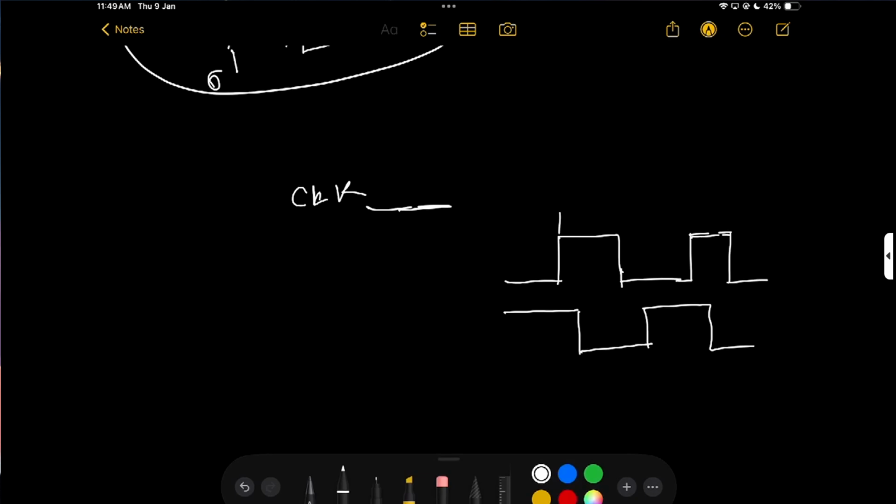So in here, in a short duration, I trigger the circuit such that my circuit is on for a small period of time, and if my circuit is on, at that time whatever the value in D, 0 or 1, goes directly to Q. So if my circuit is on for a small period of time, whatever the value is goes to Q, then it changes, and after that it holds the value.